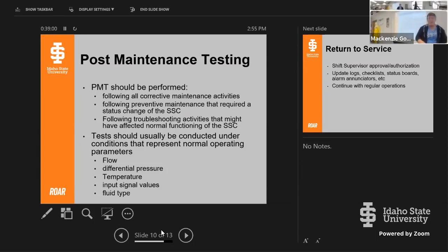One of the things that we run into a lot is we have to do drop tests with control rods. And so here at the AGN, they take that control rod out of the core and they put it on a rod drop stand, and then they drop it and they time it. And they have to make sure that the drive inserts the rod in a certain amount of time.